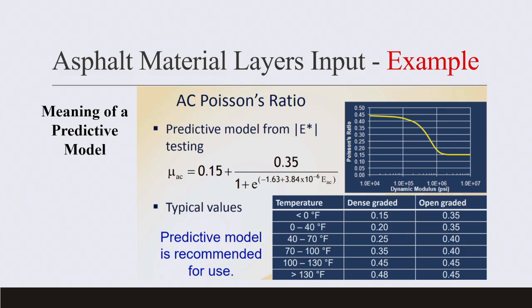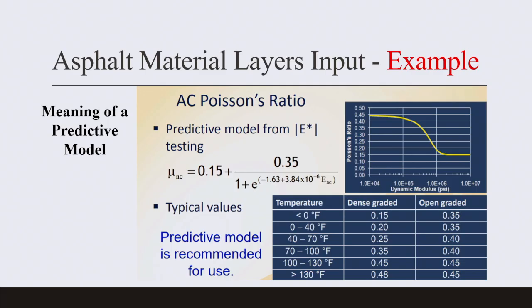Just emphasizing what I just talked about in terms of Poisson ratio and getting your E, which is the resilient modulus. Okay, so these are properties that you need to input in, and how they are temperature dependent. Also, remember your Poisson ratio is also temperature dependent. I hope you agree with me.